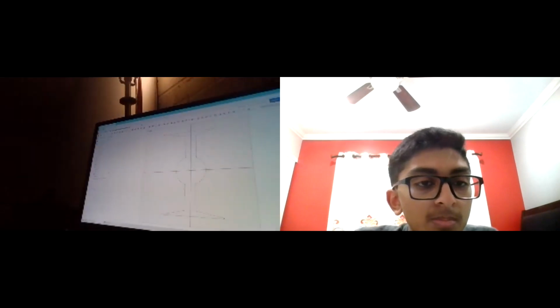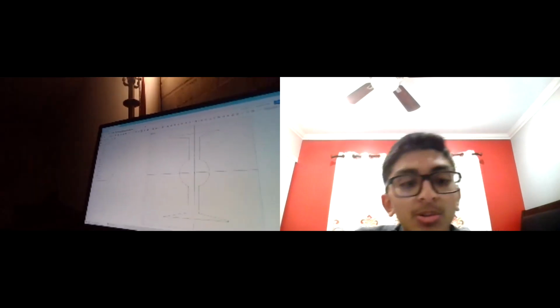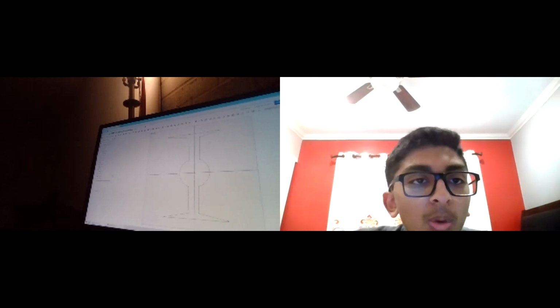Okay, so show me your screen. Okay, so at the top left, you should see the one right next to the extrude button, to the right of the extrude button. It's like a dotted line with a donut-shaped piece around it. That's the revolve option. Okay, thank you.